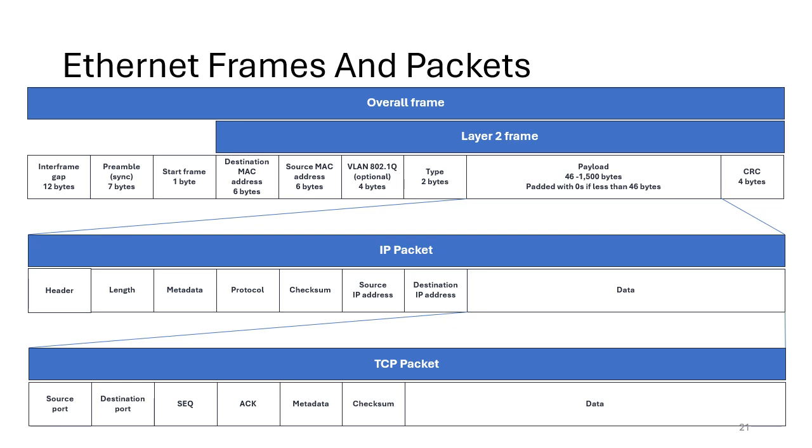I think I did some work a long time ago, and it's only one in tens of millions of bits which get corrupted, and in that case, if the message can't be recovered, it's just resent, and most systems wouldn't even notice that. The message would just be resent. You might see that at the Wireshark level, but the system itself might increment a diagnostic counter to tell you about failed messages. But in a system that's operating correctly, there would be very few of those missed messages, and the counters would all be very low.